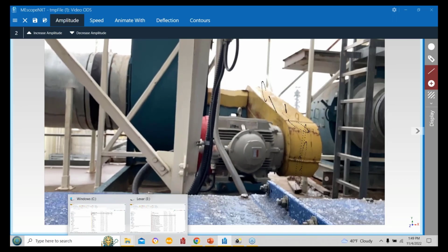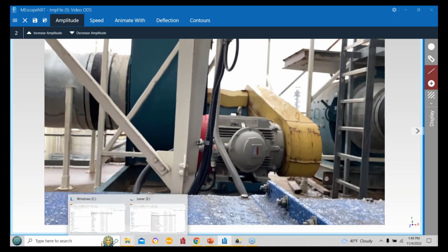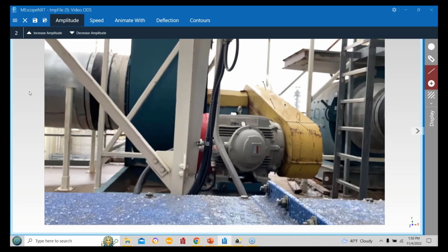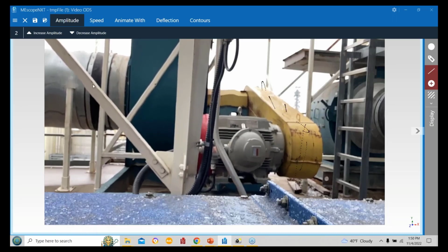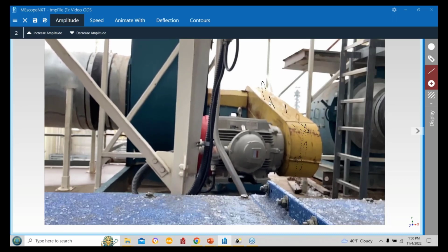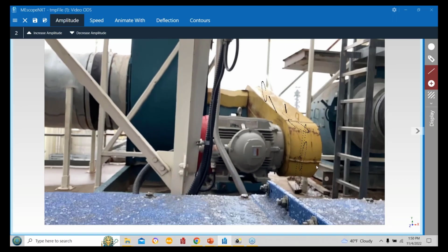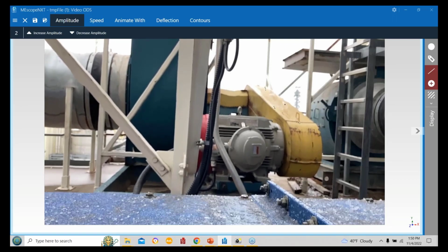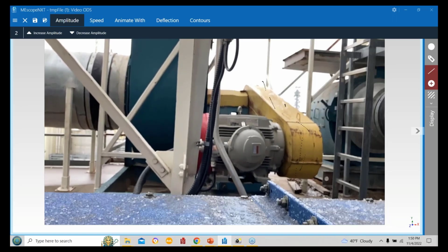If it's not bolted down correctly, you're going to get lots of response, and usually the outcome's not very good. They have their bellows in the right place, so they're not stressing out the inlet. Nice different things that they've done with this thing, but it's sitting on a roof, and it doesn't have proper isolators and it failed.